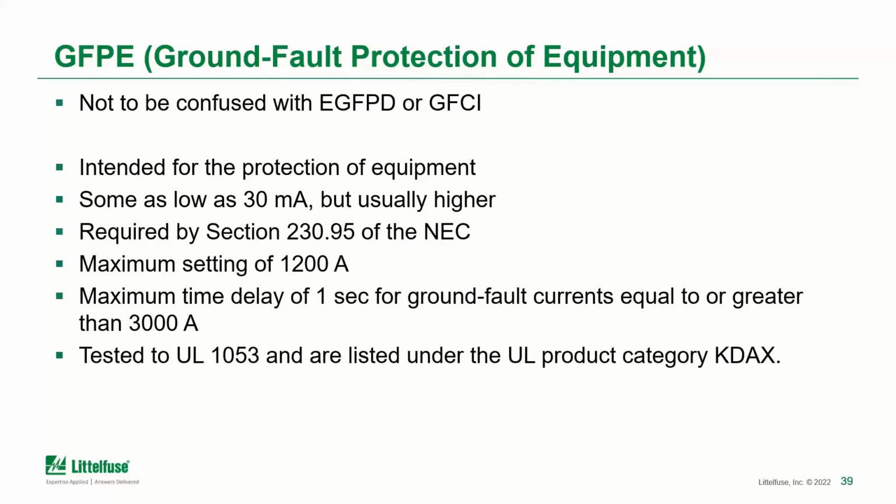These types of products are not intending to try to provide shock protection for personnel. They are designed to protect the equipment. So they're trying to reduce the damage to equipment when there is a ground fault, and prevent equipment from burning down.